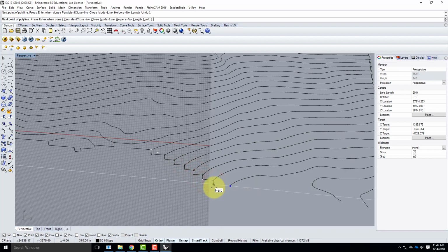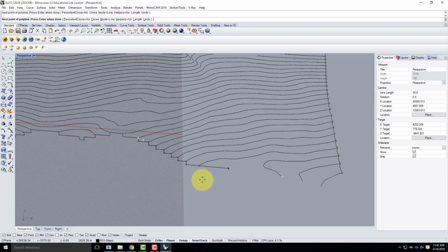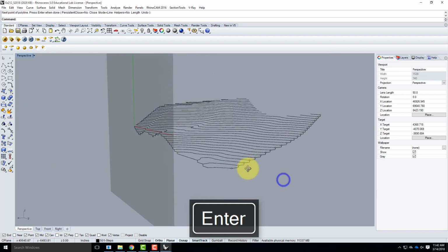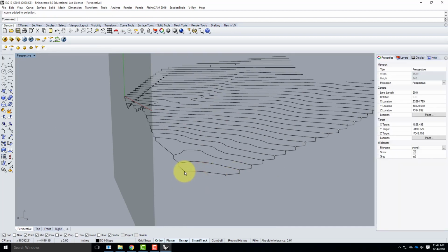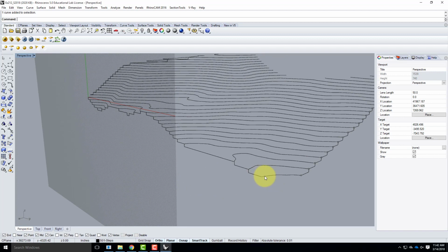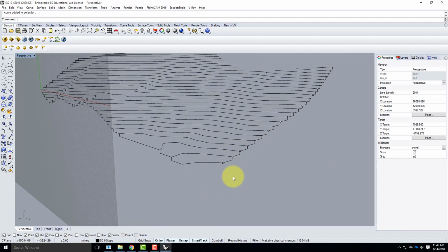So as I'm going through this, remember when we get to a set of contour lines where they don't drop down, they would be going on the bottom edge, they'd be going down your contour distance. So here's an example. This corner has a line that goes across. If I think about this corner, though, this line should be at the top of a step, and there should be one more step that goes down and then over before it meets on that particular corner. So I'm going to go ahead and try to resolve that corner right now.